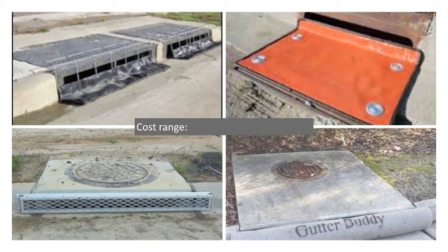The gutter buddy or recycled carpet fiber devices can be very useful, but again, make sure that there is an overflow capability, because if these get saturated, they can sag into the curb inlets. You can introduce overflow capability by inserting a half of a brick behind it and allow that capability. So if you have those and you have no choice but to use them, that's what you've got, you can put in an overflow device by putting in a half brick or a rock bag large enough that it won't go down the curb inlet as well.